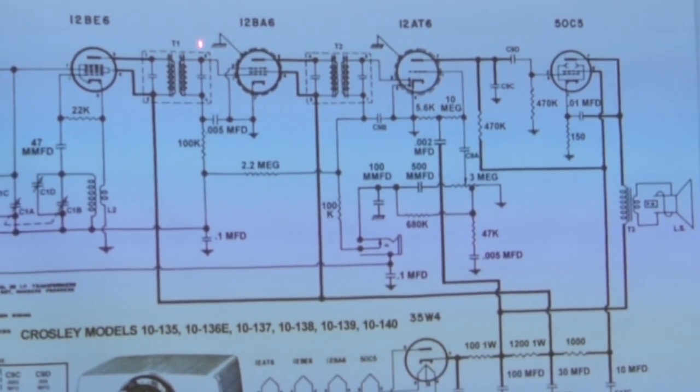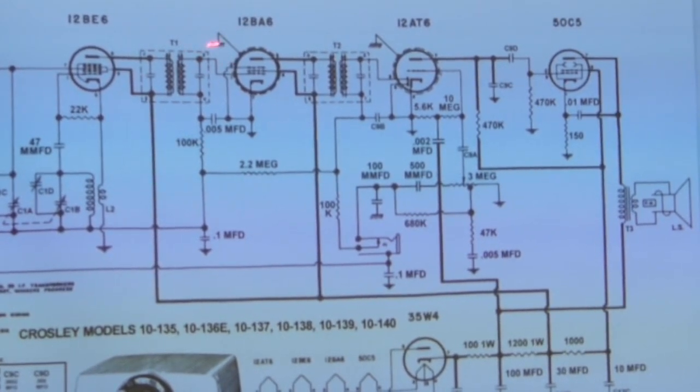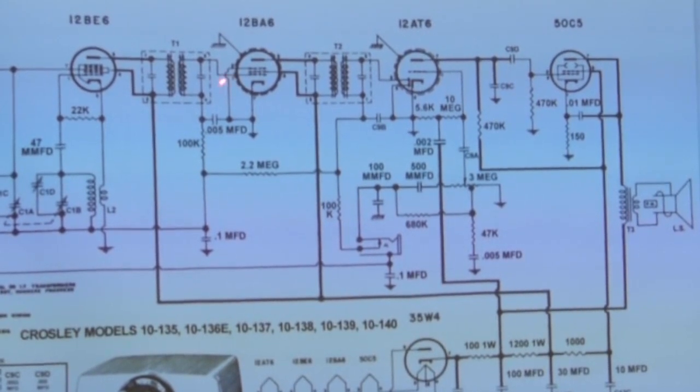But let's say that now you've discovered you've got a signal there and it is what you expect it to be at 455 kilohertz, and it goes into your first IF amplifier. Okay, all right. So then you say, great. Now you go to the back here and you put your RF probe on here and you don't get anything. Okay, what could go wrong? What's happening?